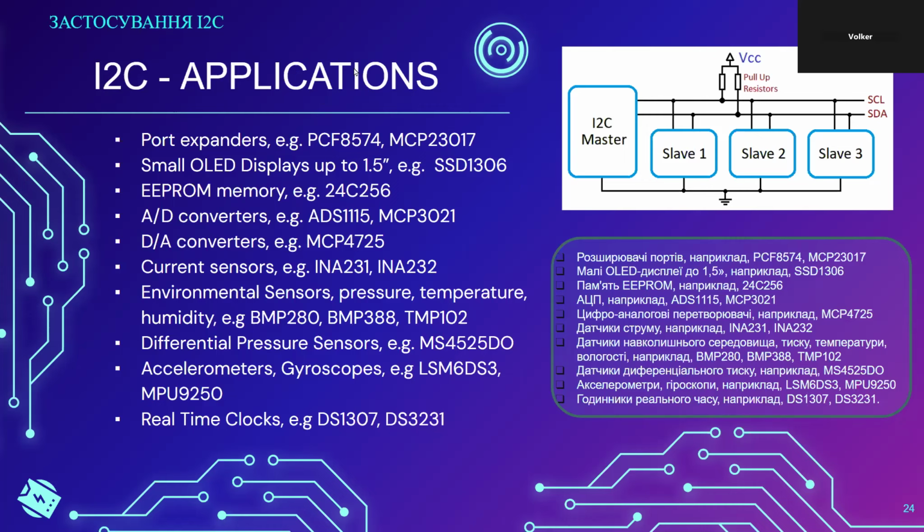What you will not find are large NOR flashes with an I2C interface, simply because the I2C interface, because of the pull-up resistors, is a slow interface compared to SPI. It makes no sense to have a 60 megabyte or larger flash memory where it takes a long time to read.